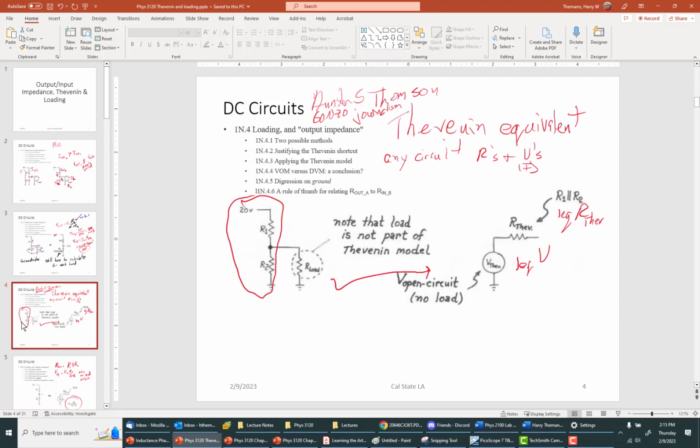And so we do the Hunter S. Thompson gonzo journalism. We go to the answer first. The answer is to convert the voltage divider from the two resistors in series with a pickoff point, the V out, into one voltage and one resistor in series. And I remind you, that's like the battery model. And I told you in the beginning without proof that R Thevenin is R1 in parallel with R2.